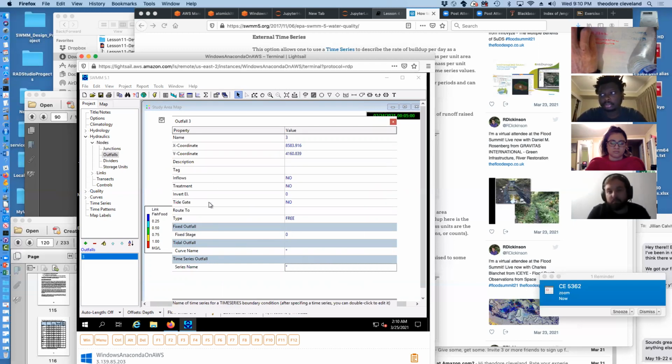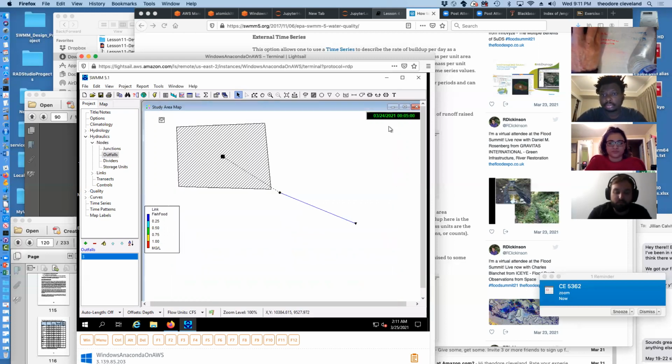I'll have to read about that, but I think we can set a value at the outfall of the constituent and use it to model a saltwater freshwater interface in a riverine system. Again, that's something I don't think they originally envisioned the program would be used for, but I think that can be approximated. I'll read how to do that.